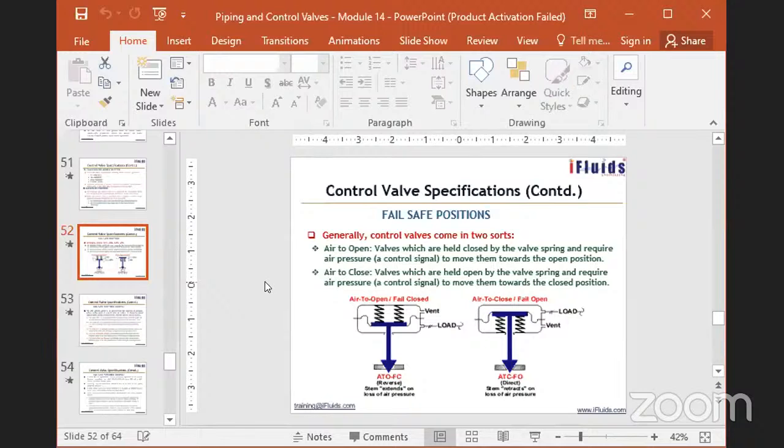They don't have very fancy internals like the control valves we have in process services. There will be a simple plate type arrangement inside. You pull the plate, and then it allows the solids to fall. There may be spillages, but it is not so serious as in process services, where wall leakage is a serious problem, because these are harmful fluids.